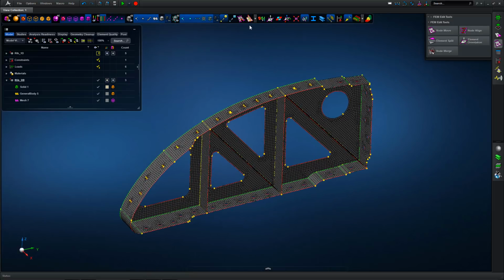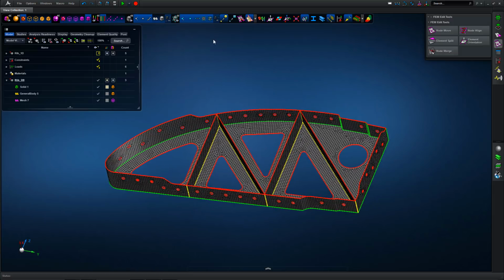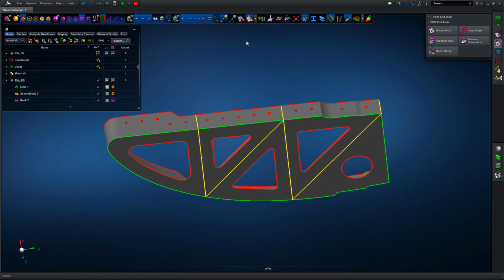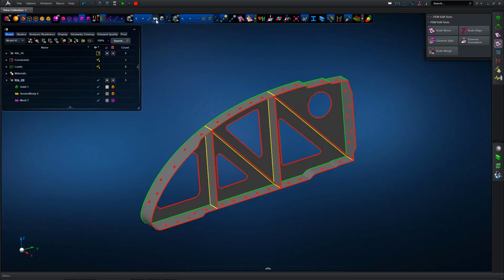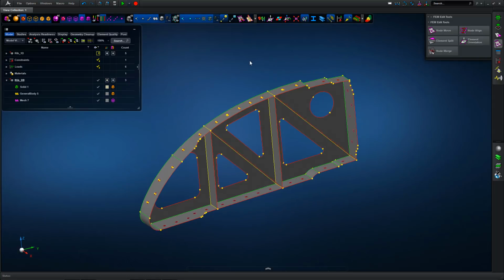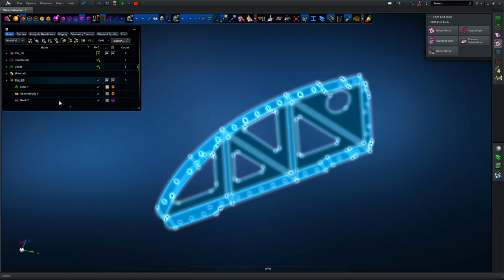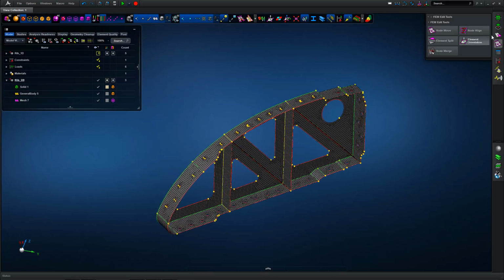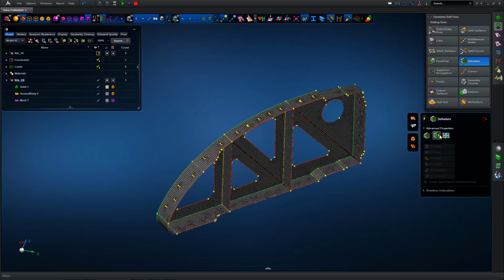So very quick to check the mid-surface shell mesh, and then surface normal updates and what have you. So we're looking at element topology, similar to the geometric free, shared and manifold edges. We can look at that on a mesh basis, so we've taken the geometry out of view, and we can see we're happy with the topology in terms of what's connected as appropriate.